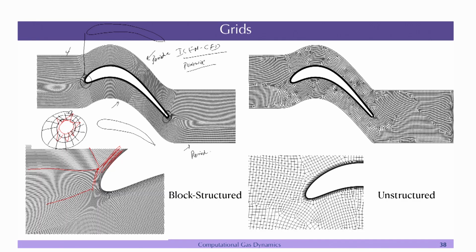The same thing is done here, there is a boundary layer grid here, but then we also have, let us say, block 1, block 2, block 3, block 4, then block 5. Block 5 for example goes from here to here, and then block 6. So, there can be multiple blocks, and making this kind of grid requires a significant amount of effort. Here also you will have many blocks, you can see in the trailing edge also 1, 2, 3 and so on and so forth.